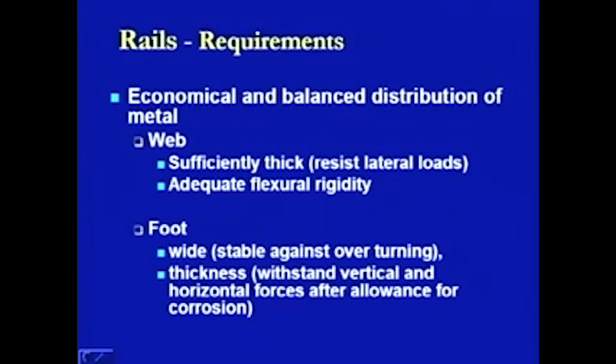In the case of the foot, because it is a point at which it is being connected with the sleeper, it should be stable enough, and so as to have that stability, it should remain wide in nature. So, if it is wide, there will not be any overturning of that material, of that component.